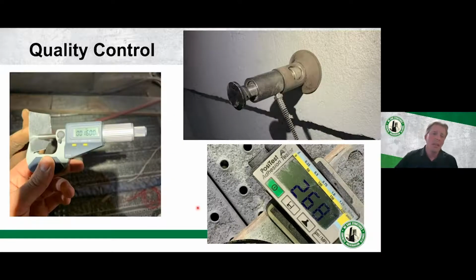Quality control. In this case, it's pretty simple. You see here, they've metallized, and we've got about 16 mils thickness, so that's an acceptable test. We've just put pieces of tape up. We do this every so many square feet or a couple times a day, however it's specified, and it's typically per operator. And what that tells you is how well that operator is installing the zinc in those areas.